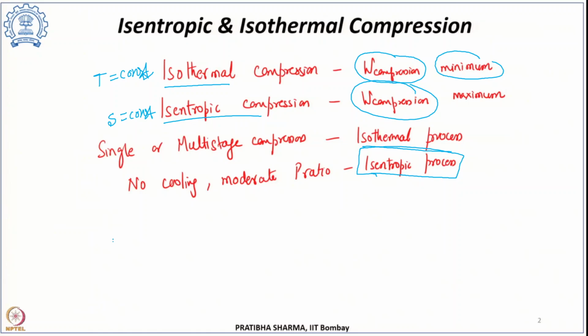because when you compress the hydrogen using one piston cylinder, the temperature of the hydrogen increases. If the temperature is very high, it can be explosive. Before explosion, you have to reduce the temperature by arranging some cooling jacket, such that the temperature will not increase. That means an isothermal process. Also we know that in the isothermal process the work done is minimum.